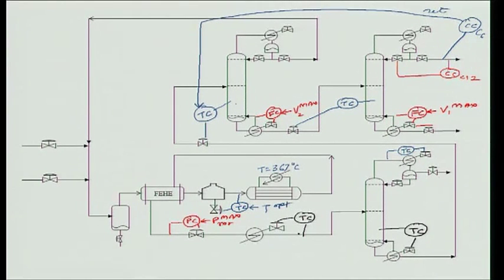I need to ensure that the reflux in the recycle column is high enough so that not too much cumene leaks up the top of the recycle column. I do it the same way as before. Anything else? This takes care of most of the economically important things that have a steady state effect. I have put in the loops.